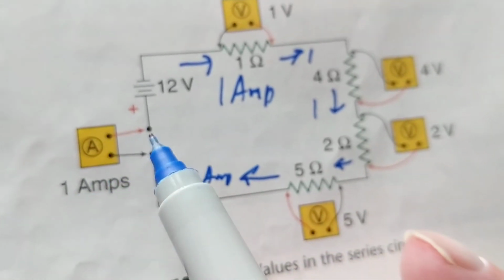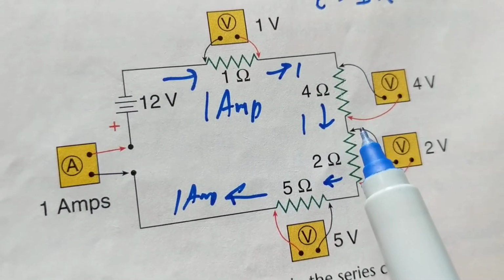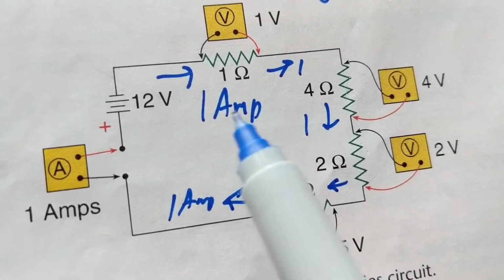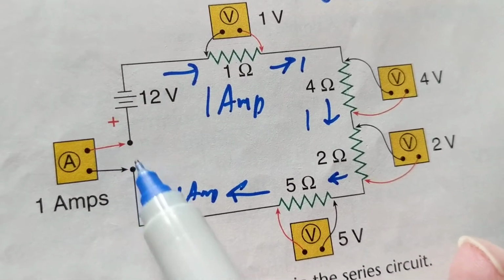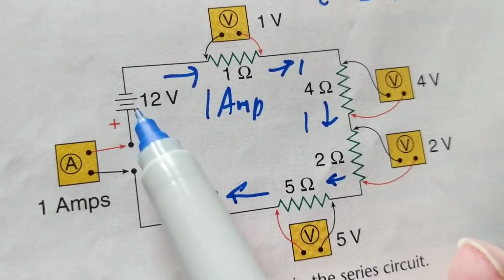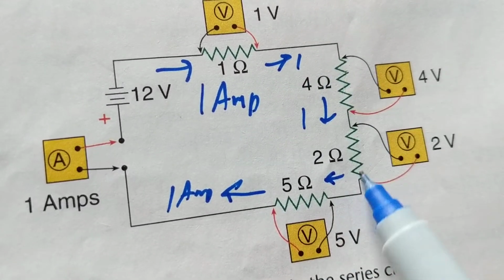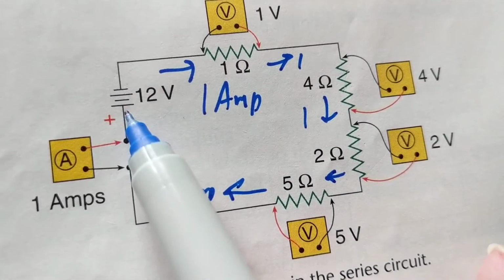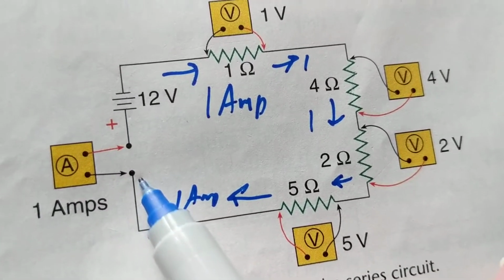He takes this meter out. Now it's open. These are bulbs. Which bulbs will light? If you said all of them, you're wrong. No bulbs will light. Once you have an open over here, why? Because current has to flow through the bulbs, and what do we say? Back to the battery. Can it do that? Nope, not if there's an open here.